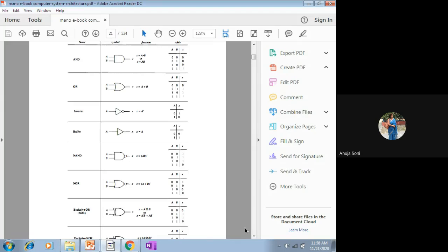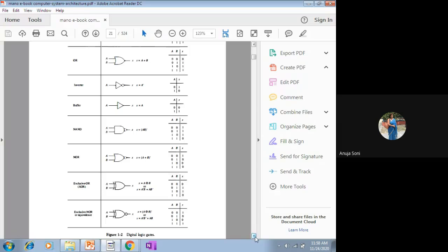Now we come to the NOR. NOR gate is again OR plus NOT. As such, the graphical notation of OR is used, but jointly this small circle of inverter is used. And ultimately it is termed as your NOR gate. And this is your Boolean expression for the NOR gate: the complement of A plus B. And this is the corresponding truth table. Again, 4 min terms are there. One output value is there.